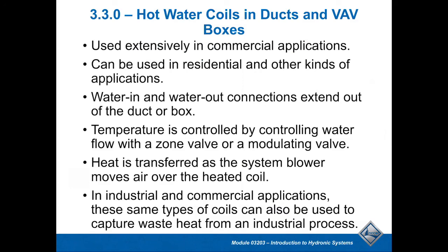Hot water in and out, obviously to a VAV box, you could have a 1-row or 2-row coil, and again, the amount of heat needed is more for supplemental heat, because most commercial jobs are predominantly cooling, so they will normally be reheating that cooler air that's blowing in the duct. So typically you'll see these more used in the external areas around the exterior of the building.